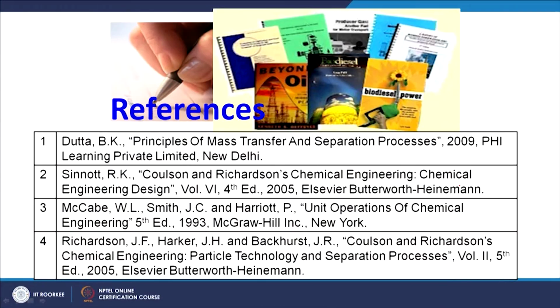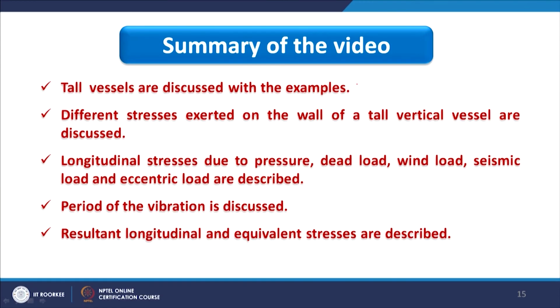Here we are having some of the references, and now we are summarizing the video, and this is basically the summary of all 5 videos available in this week, right. So, let us see that. In this, tall vessels are discussed with examples. Different stresses exerted on the wall of the tall vertical vessel are discussed. Longitudinal stresses due to pressure, dead load, wind load, seismic load and eccentric load are described. Period of vibration is discussed.